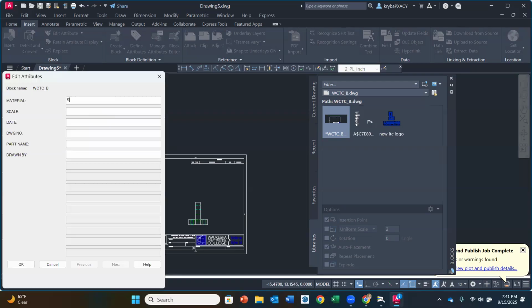So this will be steel again. Remember, all caps. I take off points if it's not all caps in the title block. My scale this time is 1:2. So whatever you pulled it in at, that number is going to be after the colon. It's kind of like we had to make the border 2 times bigger. So whatever is on there is half the size. Okay. Even though we always draw 1-to-1, don't worry about that.